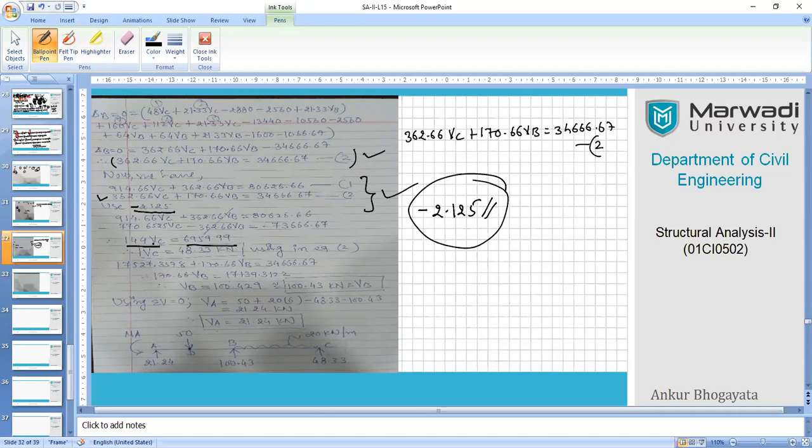So it is 144 because 914.66 minus 770.6525. I have worked it a little precisely so that we get good results. So out of this we can get the VC value: 144 VC equals 6959.99. So you will be getting your first answer in terms of VC, that is 48.33 kilonewton.